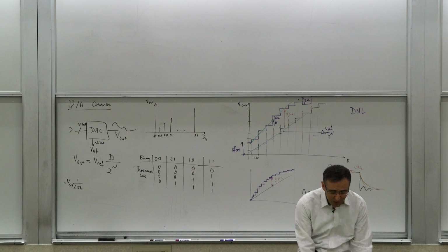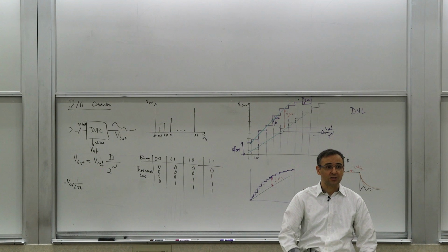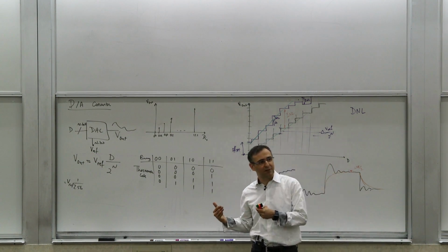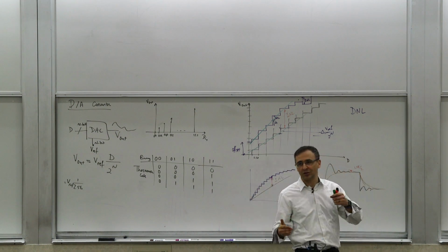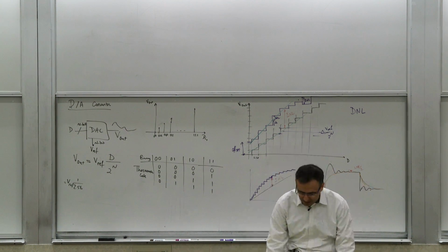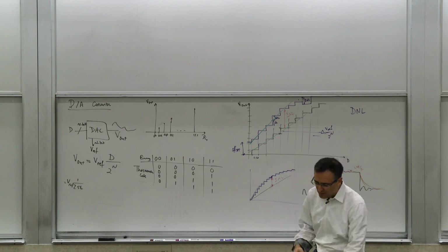And you will see when we talk about architectures, especially the A to D architectures, that some architectures really exploit these trade-offs. Some of them have a higher sampling rate, higher latency, or you can change the complexity or the power consumption, and you can trade this with the architecture.